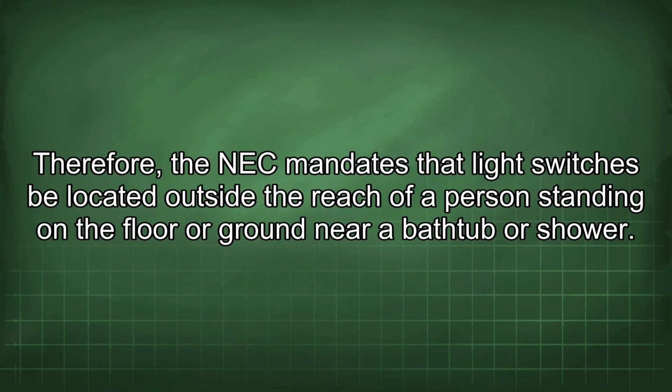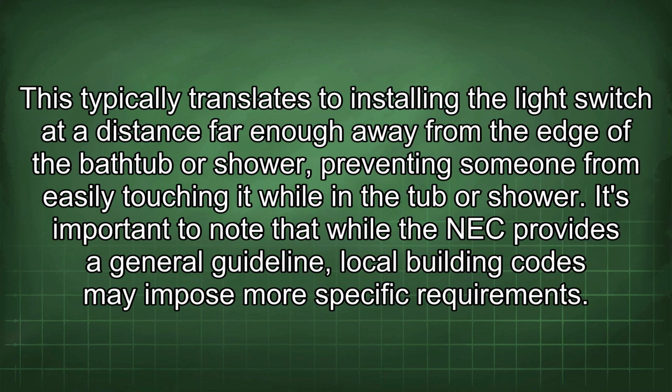Therefore, the NEC mandates that light switches be located outside the reach of a person standing on the floor or ground near a bathtub or shower. This typically translates to installing the light switch at a distance far enough away from the edge of the bathtub or shower, preventing someone from easily touching it while in the tub or shower.